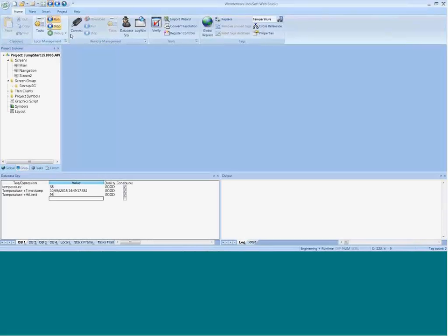So here right now it's set at 95, and when I cross that 95 threshold, it'll go to too hot. If I put it back down in kind of a lower range, let me acknowledge both of these alarms to get those off the screen. And now let's say I want this to be at 75. I've got a new limit. Why didn't that take? I know why, because I didn't stop, because this is a pretty major change to my tag database. So I need to stop my project and then rerun it to get those properties to take effect.